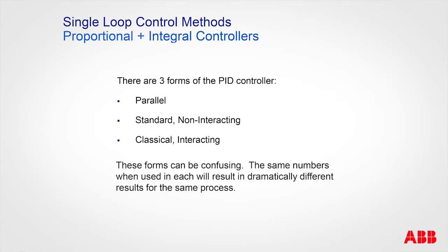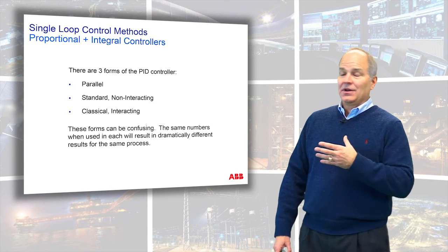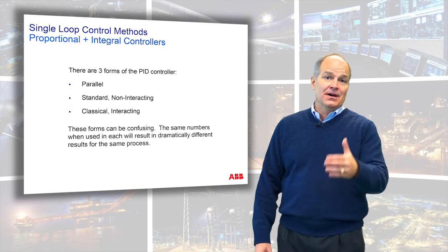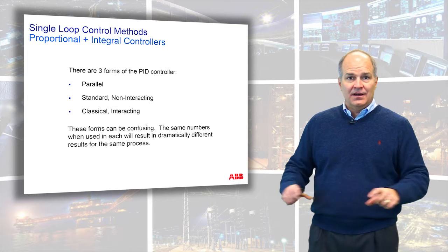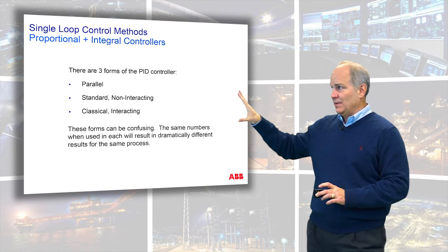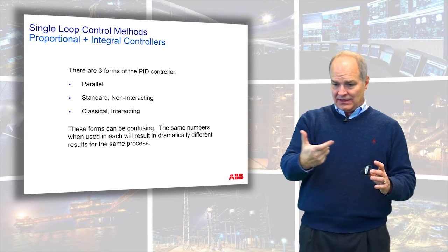The parallel form is with our Infi 90, Harmony, the Bailey control system. The standard or non-interacting or ideal form of the PID algorithm is used in the Master, the 450, we call it a PIDCon. And then the classical interacting is actually the Mod 300 or the Taylor series. So in the book I have a whole list of different manufacturers, and I still recommend after this discussion you'll be able to look at the pictures and the algorithms and go to the manufacturer's book and see what type